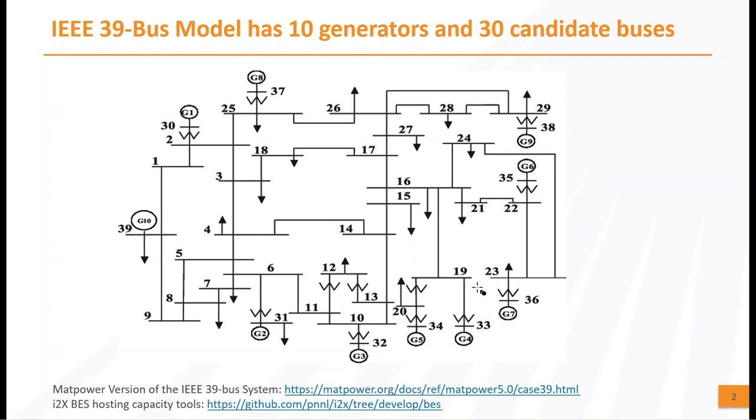But the focus of this example is really how to automate the contingency analysis. Once the load flow dispatch is set up, we want to do faults and clearings in and around bus 14 with this line out of service, and then again with this line out of service, and finally with this line out of service. And the fault is going to be right on the terminals of the line, right outside of bus 14. So for example, right here, right there.